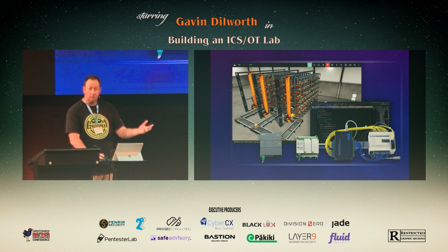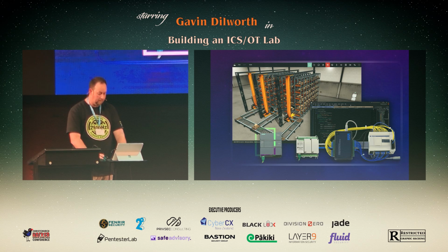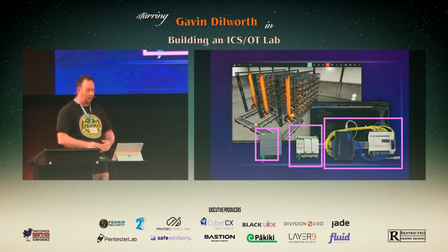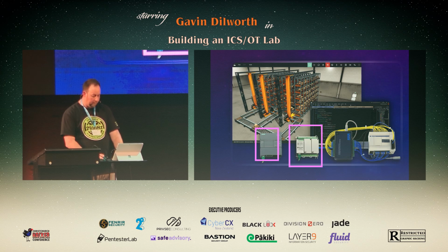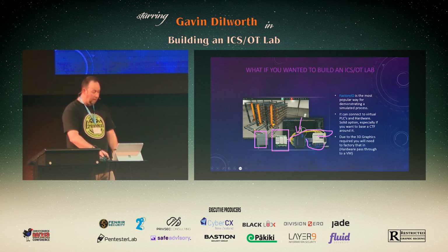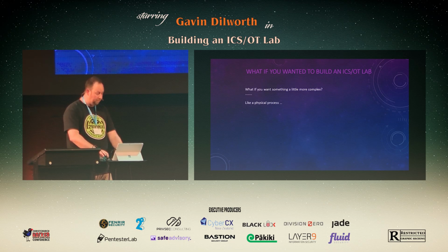It can run on OpenPLC, it can run on CodeSys, it can run on real PLCs, like Siemens here, Allen Bradley, Telesys, connected to actual IO. So this is actually simulating a physical process from Factory IO. Factory IO essentially talks to this and simulates the on-off inputs, outputs, analog transmitters. Those all go into the PLC, and then the PLC executes the code. So once again, hybrid as well. So plenty and plenty of options.